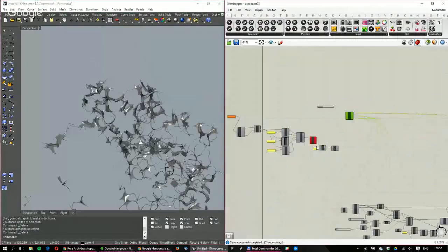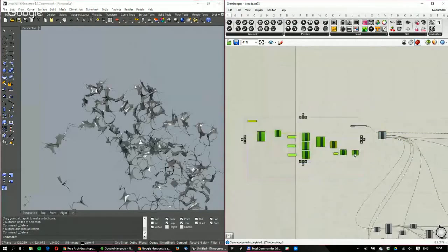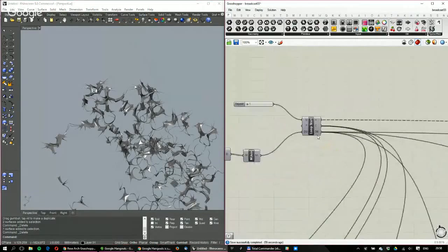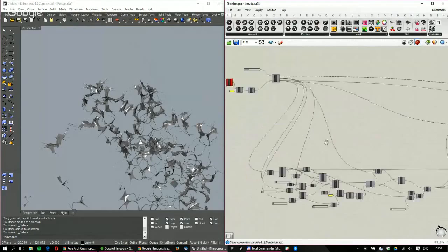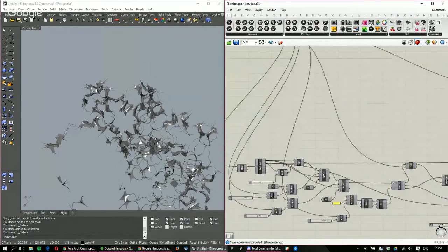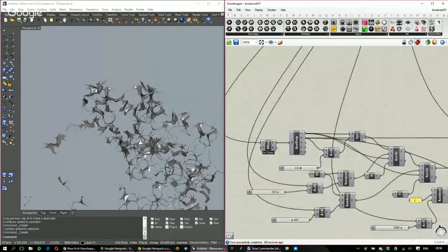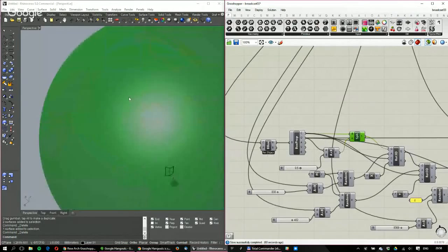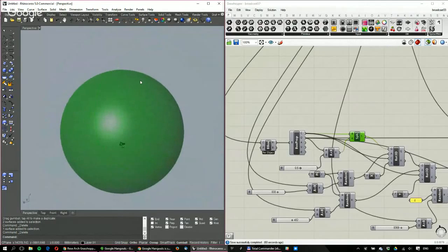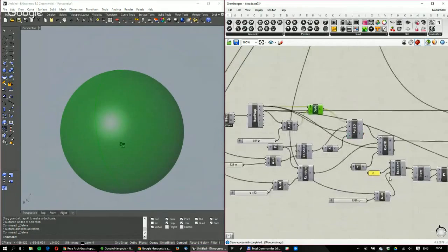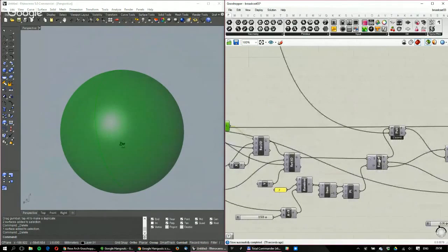So once again, what we are doing from the bounding sphere. So basically now we are in a loop. And the loop is actually creating a diffusion limited aggregation. So the diffusion limited aggregation works like this. We need to have a sphere that is bigger than your entire geometry, which is this one. And you select a random point on the sphere, which I'm doing here.